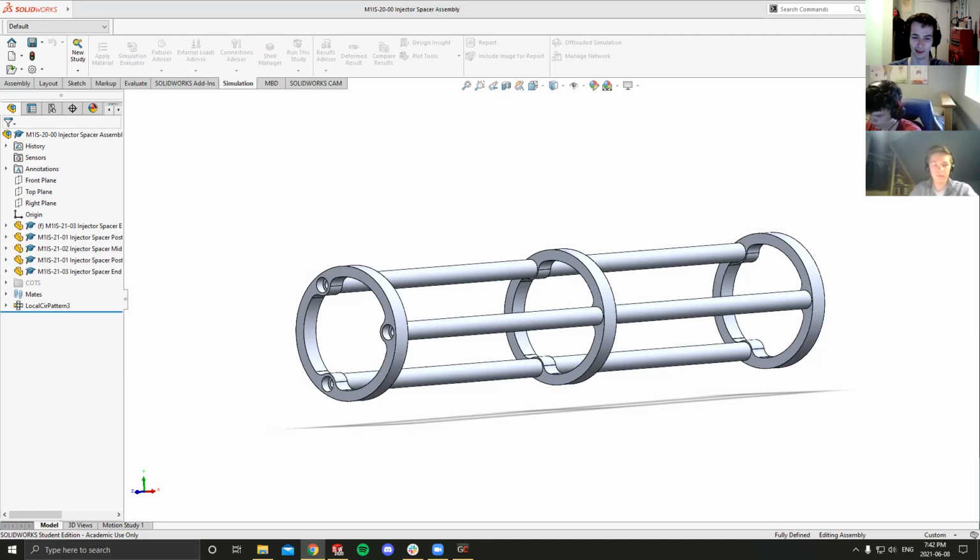That's very important for designing anything mechanical in nature. And so, secondly, you will need to know what loads you're expecting on your parts. You need to know how your parts are located or fixed. And simulation should always, or when possible, be backed up by hand calculations to verify your solution.